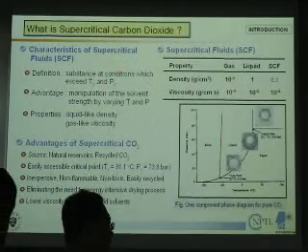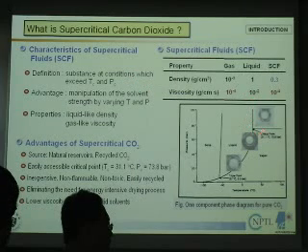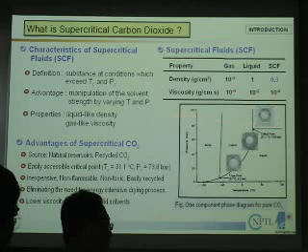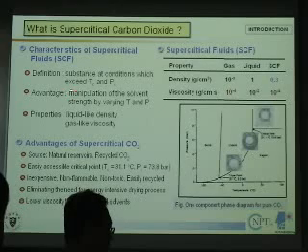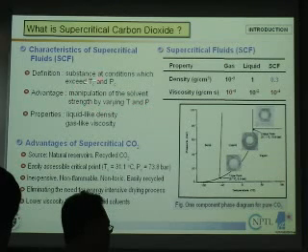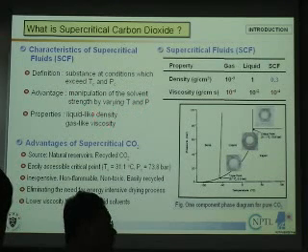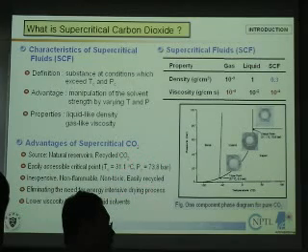So as you know, the supercritical fluid we use here is the carbon dioxide supercritical fluid, and supercritical fluid means once you reach this critical point, that fluid acts like liquid-like density and gas-like viscosity property, and that has this kind of advantage. Manipulation of the solvent strength by just changing the temperature and pressure. This is the key concept to apply to our system. And this is another advantage by using the supercritical CO2, but I'm not explaining this in detail.